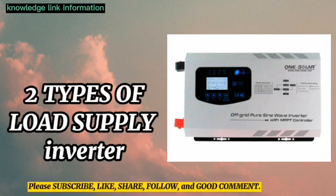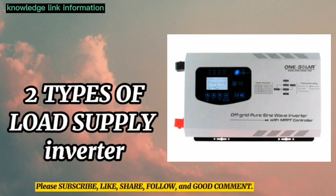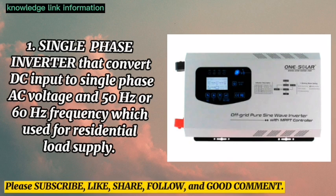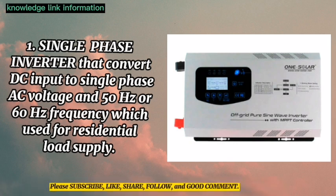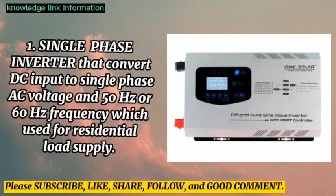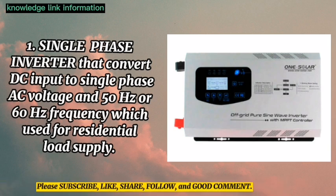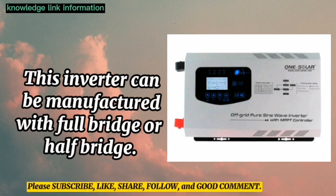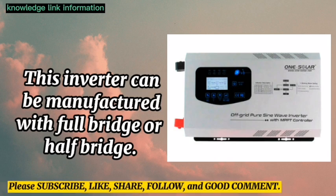Two types of load supply inverter. Number 1. Single-phase inverters convert DC input to a single-phase AC voltage output at 50 or 60 Hz frequency, which is used for residential load supply. This inverter can be manufactured with a full bridge or half bridge.